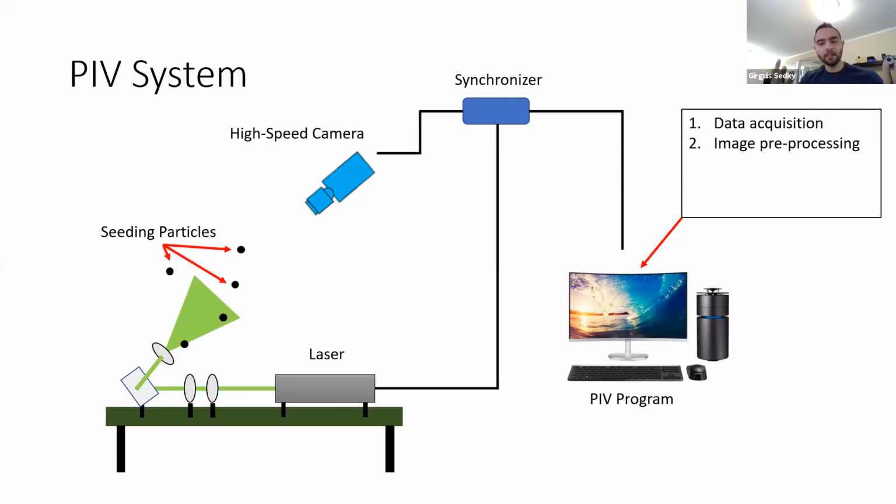If you take all the images you've taken, average them all up and subtract out that average image, you end up with images that don't have that background. So you'd end up with images with purely seed particles and nothing else. You do the PIV cross-correlation, vector validation, and post-processing to get vorticity or whatever flow quantities you'd like to get.